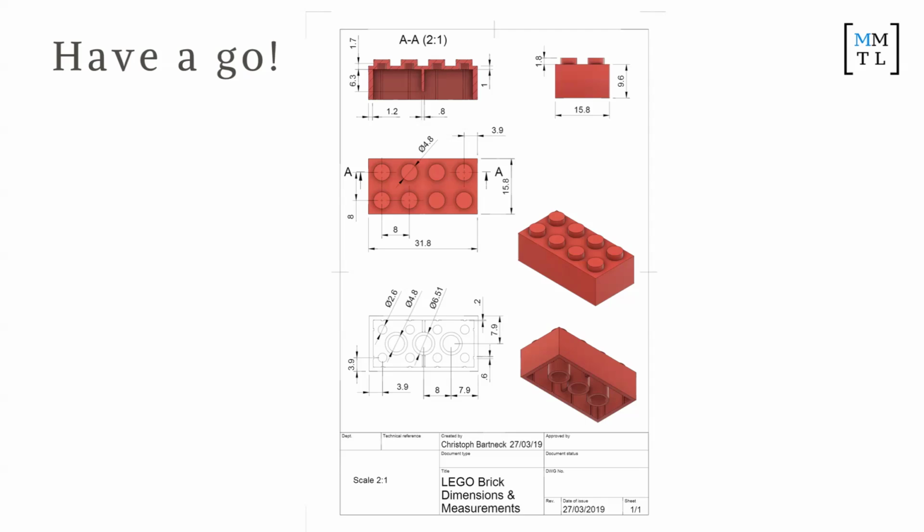What were you thinking? If I just make circles offset and then get them in. So you have to have a construction plane first, right? You've already got the construction plane? I did it because I did 8.6. Okay, yeah. So create a construction plane. Actually, I probably would have to create one.